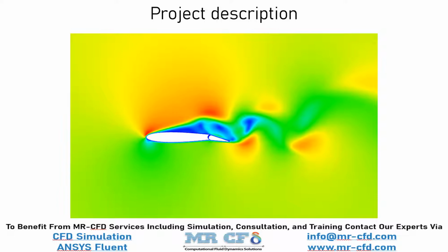Moreover, the drag coefficient of the airfoil in the presence of flap is equal to -0.0273, which is less than the airfoil without flap, where the drag coefficient is equal to -0.0822, which proves that the flap presence is effective in drag force reduction that is favorable in aerodynamics applications.